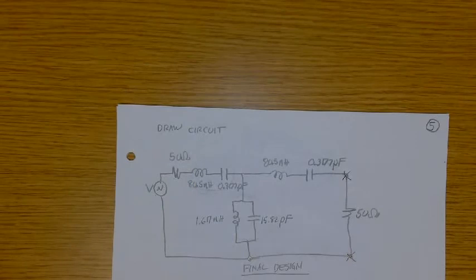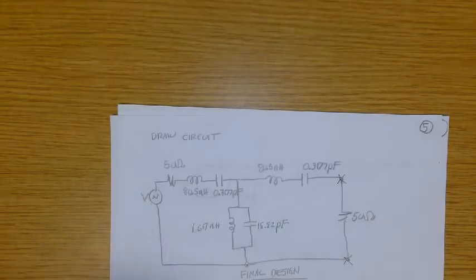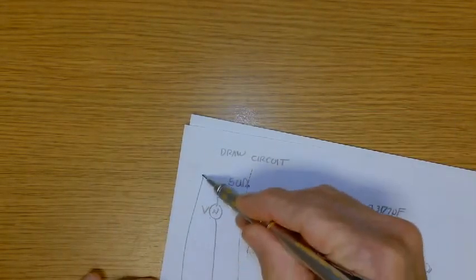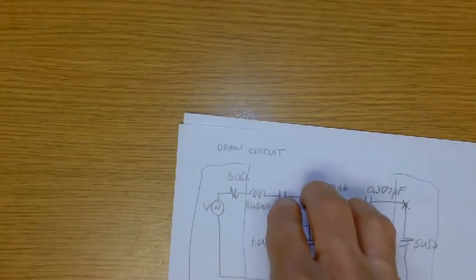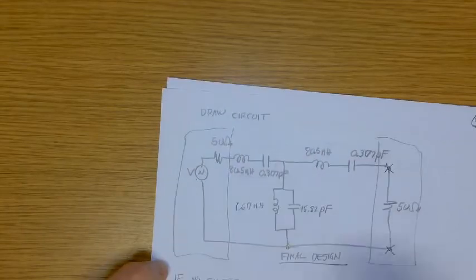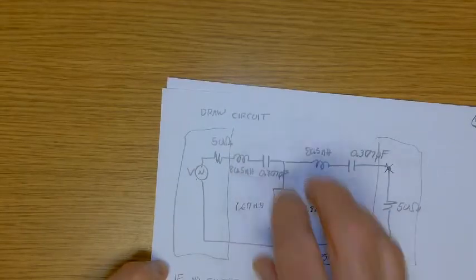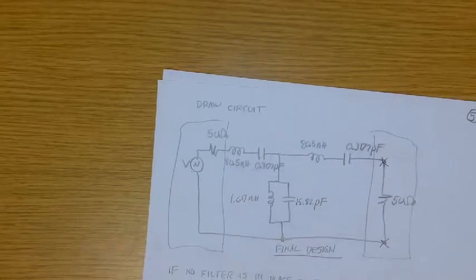Well, since it's a band pass filter, there should be a range of frequencies over which the insertion loss is low. Outside of that band of frequencies, the insertion loss should be high. And based on the design, the order of the design sets the skirt slope going from band pass to band stop, and also the amount of ripple that we're allowing in the pass band. In this case, 1 dB. All right, so all of that.